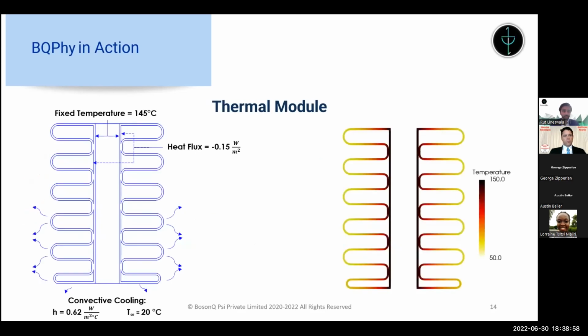The next module, this thermal module, again, we took an automotive example, where this is a radiator in a car. So in this case, our regular automotive radiators are 3D, but since it's the same shape, kind of extruded into the third dimension, we can very well just do the simulation as if it's a 2D based simulation. And so these are all the boundary conditions where you have your fixed temperature in the center column, and then you have your heat kind of radiating outward, and your convective cooling, since your car is going to be moving. So that's going to be cooling this whole radiator.